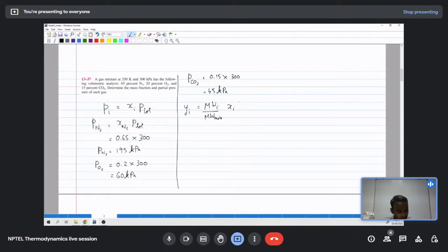So Xi will be in mole per mole, and molecular weight will be in gram per mole. So this will be again in gram per mole. So when we multiply gram per mole into molar fraction, we get the mass fraction of the mixture of the gas. Now for this calculation we need the molecular weight of the mixture.